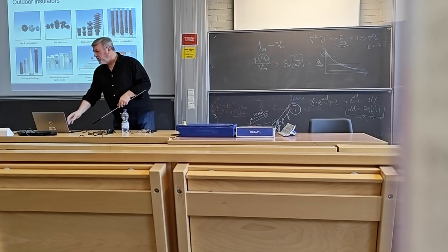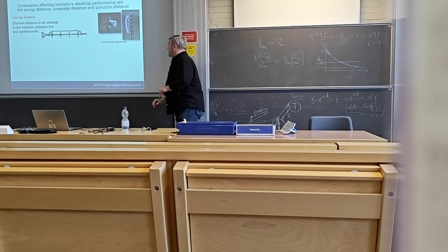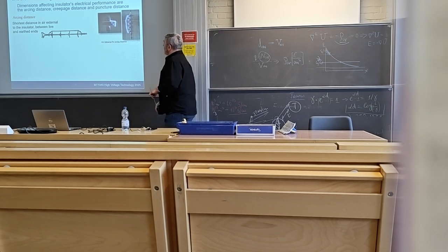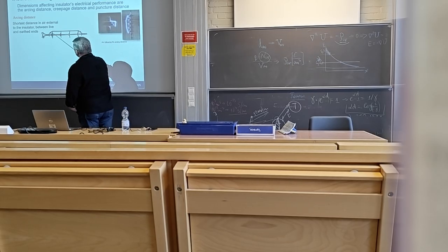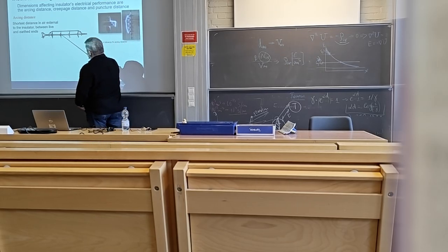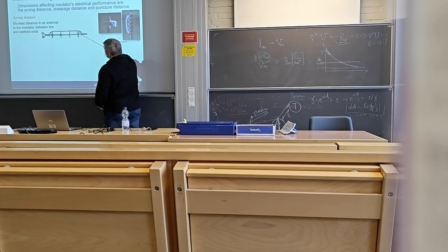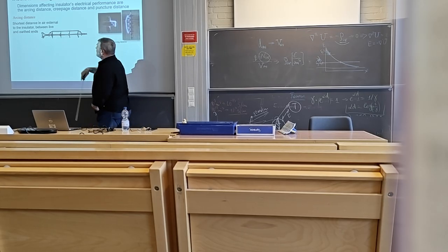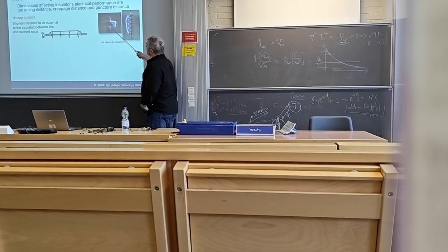So, what is common when considering the possible flashover path? So if this is the insulator, it's a composite insulator. You see the glass reinforced plastic core, then the housing, these sheds to increase the creepage distance, but the shortest distance between the energized parts is called the arcing distance. That's how the flashover happens, from this to these metallic elements over the air, basically, like that.